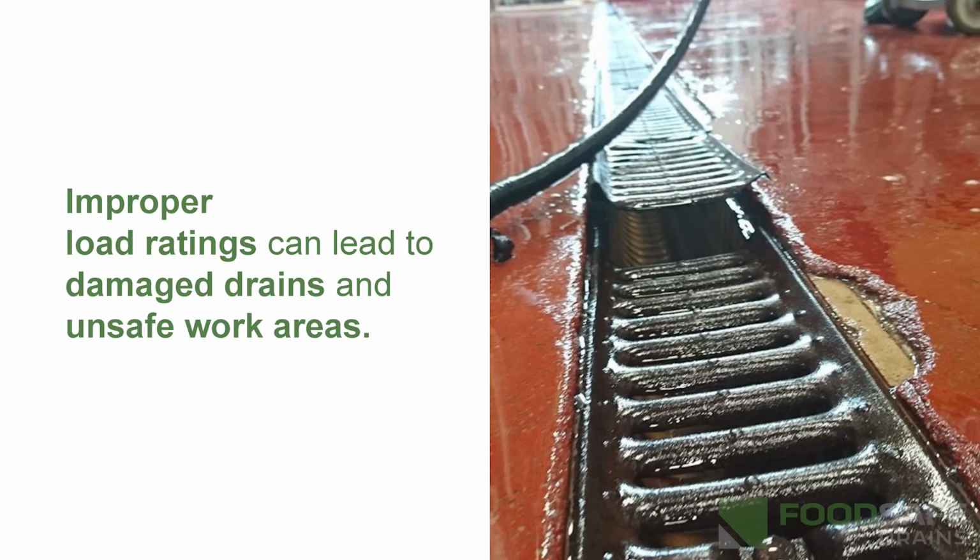I love this photo because it says so much. Clearly they selected the wrong type of drain system for an area that was maybe seeing heavy traffic. And you see that not only has the grate bent and created a hazard, but now that whole drain is flexed and pulled away from the concrete. And so now we've got water intruding beneath the drain, beside it and into the concrete. The floor coating is chipped away because it was installed improperly. There's no keyway along that drain, which means that floor coating cannot bond directly to the drain.